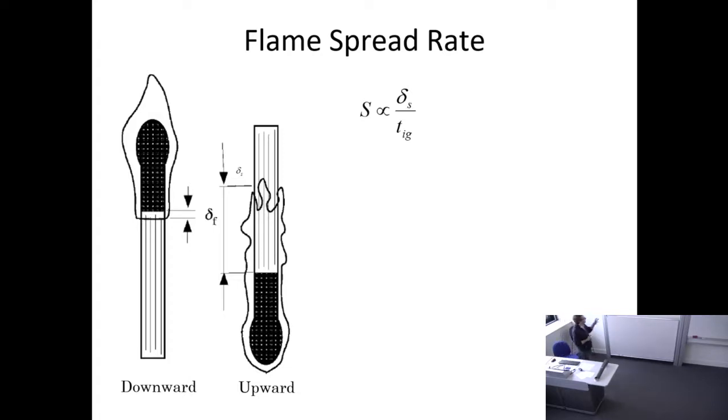So if you do that, and S is the speed of the flame, how you have a flame that is developing. If you look at the leading edge, the velocity of this leading edge is actually the flame spread velocity. Nothing to do in orders of magnitude or the reason why it's burning to the flame speed of a premix flame. Okay, a premix flame is really fast. Remember, for methane, it's in the order of 30 centimeters per second. It's really fast. These flames in a solid are much slower. We're talking about 30 centimeters per minute or something like this.